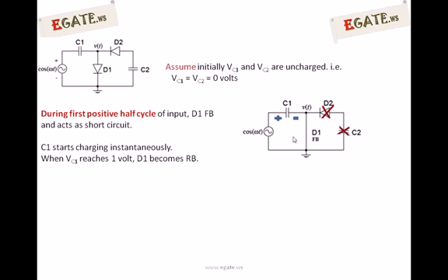So at t equal to 0, the cos omega t input signal gives plus 1 volt, which is taken by capacitor 1 at that instant itself. So at t equal to 0, capacitor 1 has reached plus 1 volt. Capacitor 1 takes plus 1 volt in this direction, as indicated by plus and minus, since the current is flowing: first you get the positive terminal, next the negative terminal.